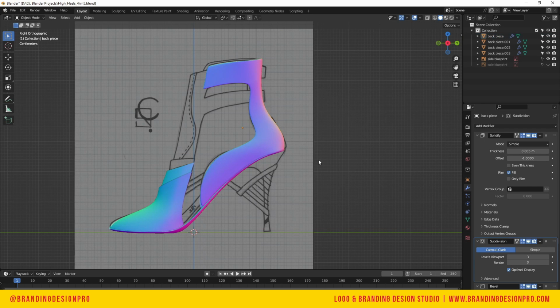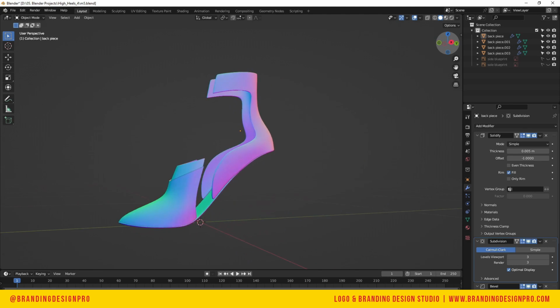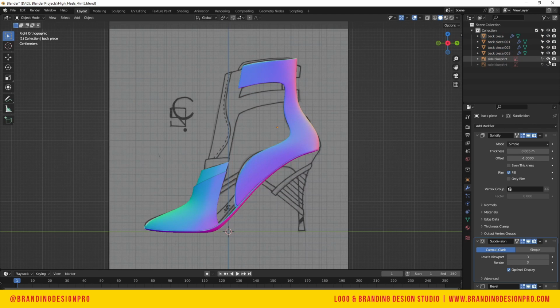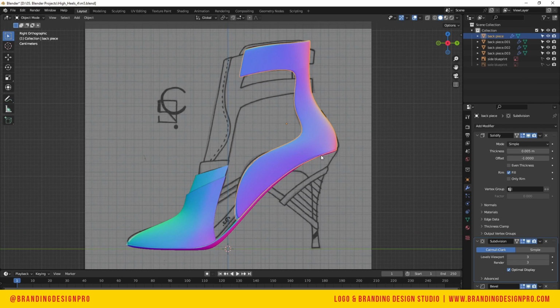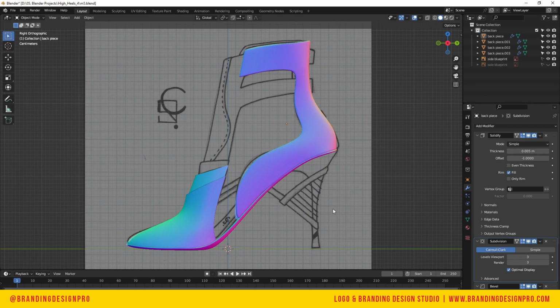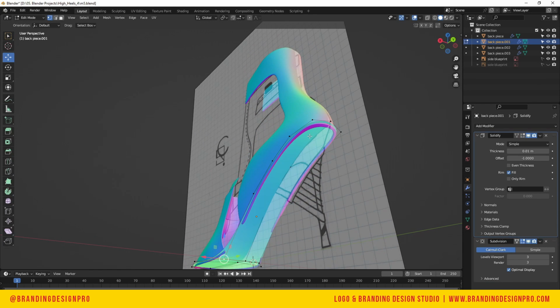Now, to complete the back part of the shoe, that heel portion of it, we're going to, again, copy some of the geometry, but we're going to do it from the bottom. Let's just adjust that a little bit. Oh, I'll leave that alone. Then let's rotate it a little bit. Select that bottom sole, go to face selection mode. Select the 4 faces towards the end.